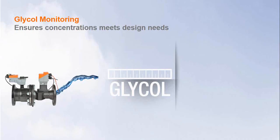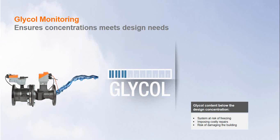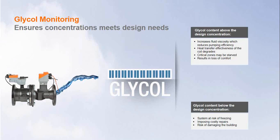With glycol concentration that is below the design concentration, there's a natural risk of the system freezing. And if the system freezes and pipes break, you could have costly repairs throughout that system. It could also damage the building. So if a valve were to break over a server room, for example, that could be a very costly repair to rectify that situation.